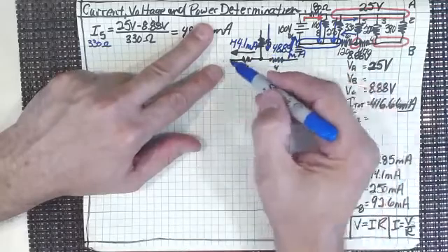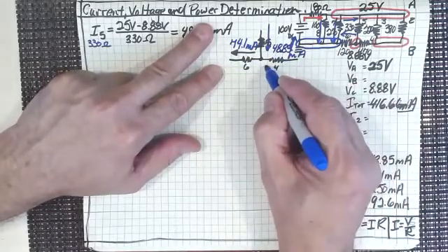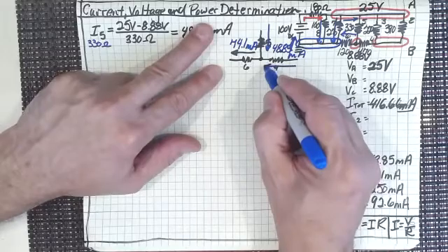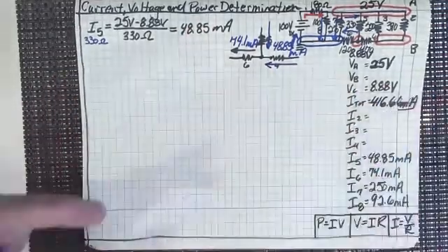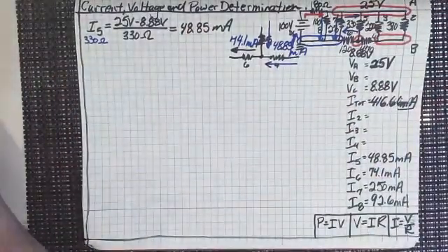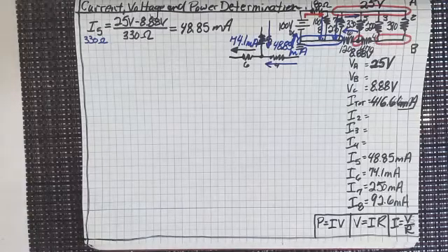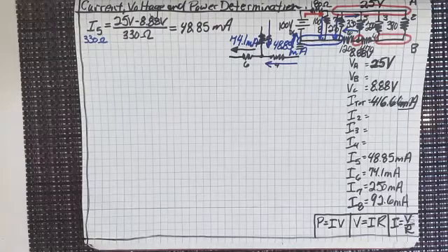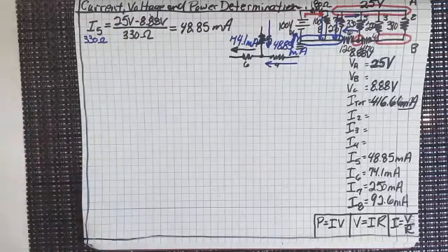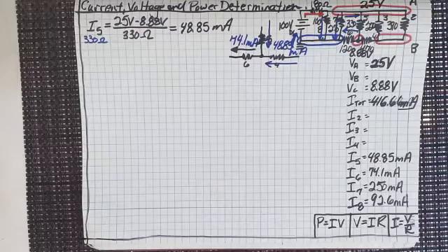If that's coming in and that's going out, what that means is that this has to be coming in too, doesn't it? And what is the current that's going to be flowing into that node? We know that the summation of currents into the node has to equal 0, right? So we've got 74.1 milliamps flowing out, 48.85 milliamps flowing in through I5.